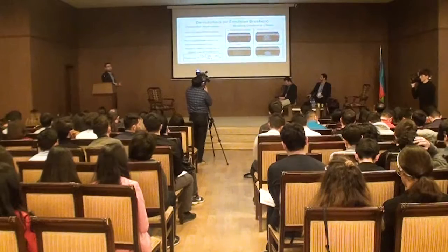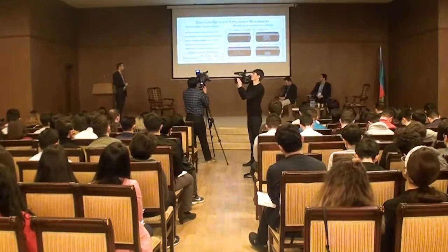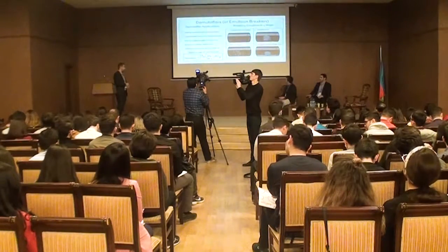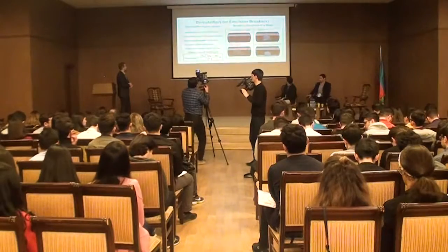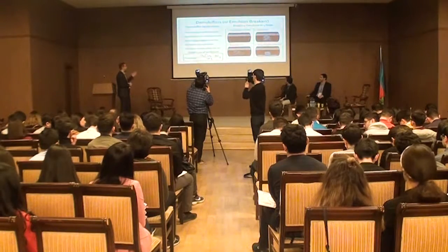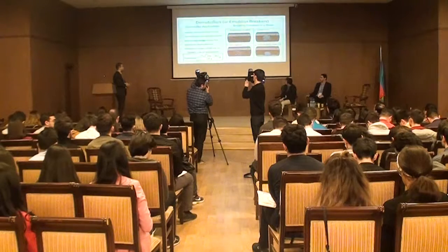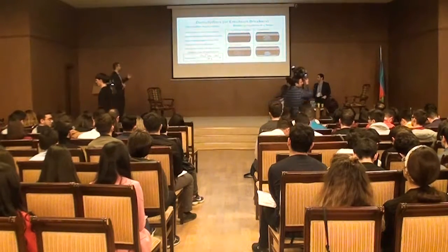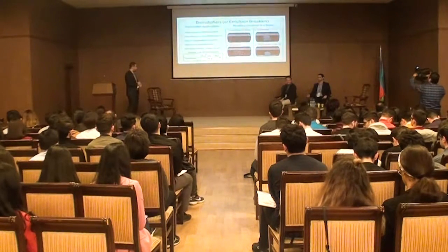So first of all, demulsifiers. They are also called emulsion breakers. Emulsions are undissolved particles dispersed in immiscible solutions. So we use this kind of chemical to demulsify the system. These applications help us maintain 5% water or even lower water content in the system. They're usually injected upstream of the separation vessel. Where we have separation vessels, before that vessel, we need to inject this chemical to get as much efficiency from it as we can. And imagine this is a separation vessel.